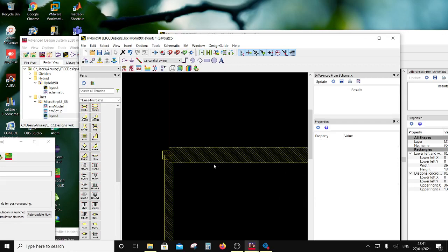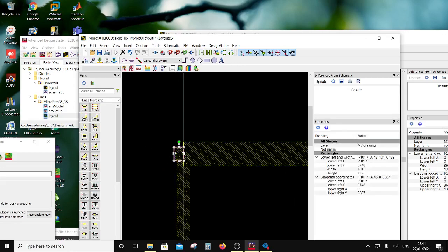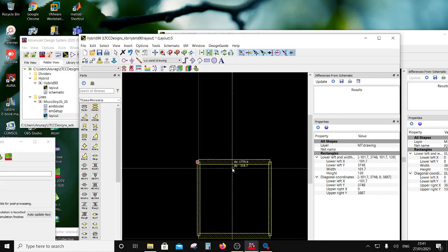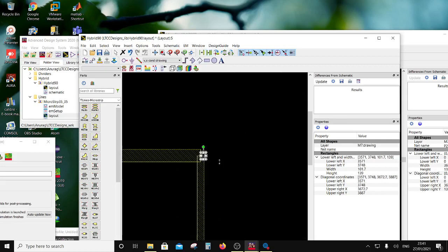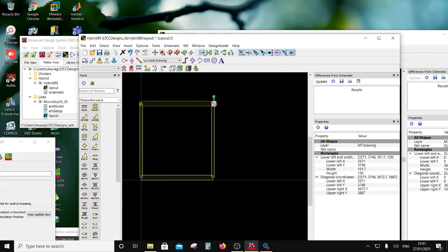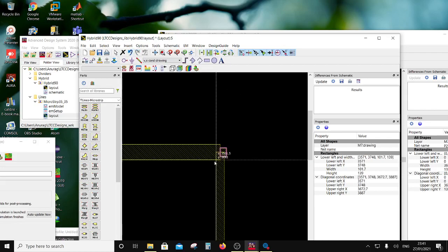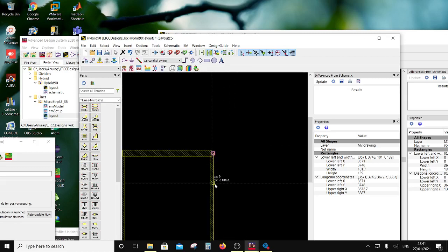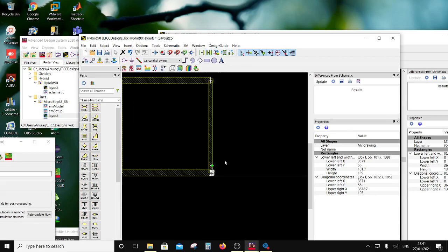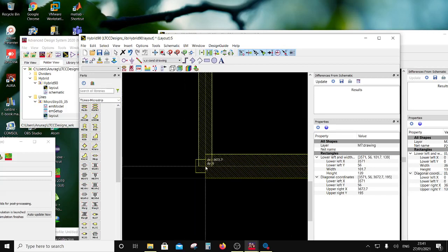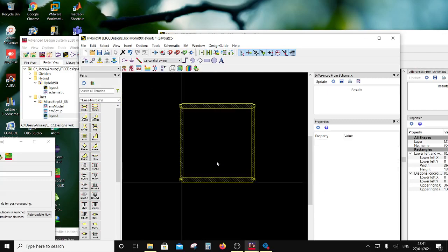So that's a small piece of line. You can extend to any extent you want. If you want, you can make it double. Doesn't matter. It's just that you should know that the phases will be referenced to something rather than being absolute numbers. Okay, and I'm going to repeat that. That would come over here, and another one would come over. So this is a 50 ohm extension because this port has become 50 ohm. Correct. So now we are done with it.